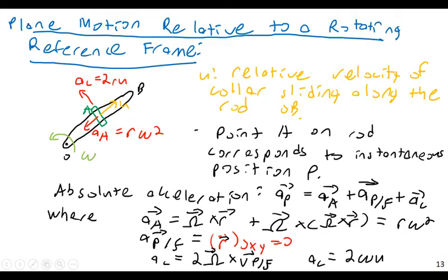And then I can summarize by saying the absolute acceleration consists of the radial and tangential components shown. The tangential component is the Coriolis acceleration, and the radial is the AA we mentioned previously. 2 omega U. Where, right here? AC equals 2 omega U, I believe. No, there's 2 RU on the top left of the diagram. Oh, sorry about that. Yeah, that's 2 omega U.